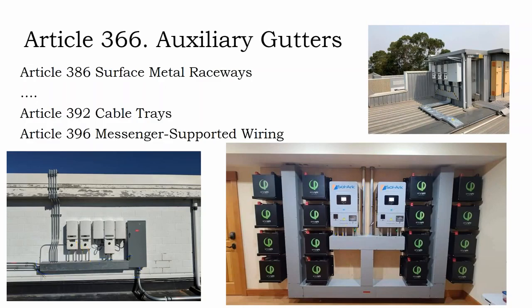And what does that gain you? Why do we use these gutters? Well, because otherwise you would have to take this run, and let's just assume this is from a solar array and it's landing on this inverter, or maybe it's probably going back to the electric service panels. The solar stuff, I'd say, is going to come in through here. But if you didn't have these gutters, you would be running conduit down and looping it around on the wall in these big loops. And then you might have multiple conduit runs.